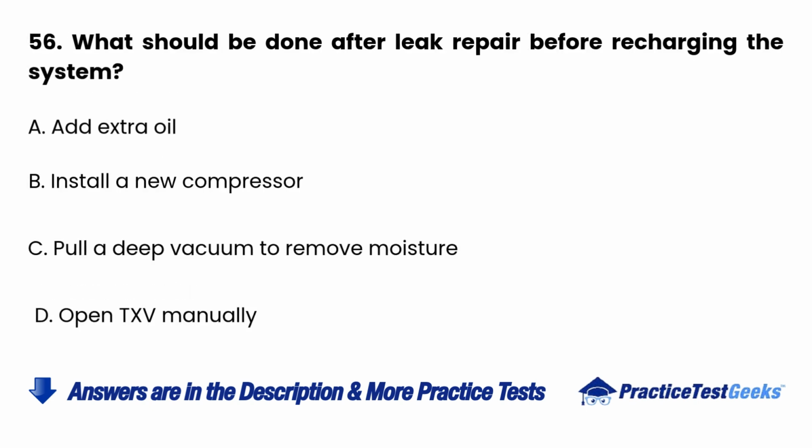56. What should be done after leak repair before recharging the system? A. Add extra oil. B. Install a new compressor. C. Pull a deep vacuum to remove moisture. D. Open TXV manually.